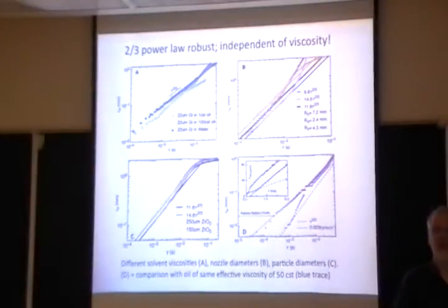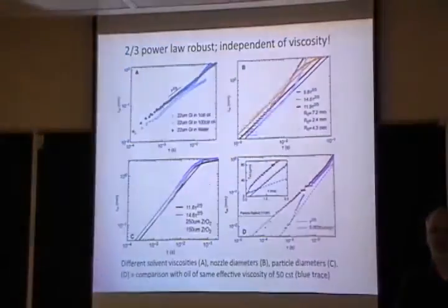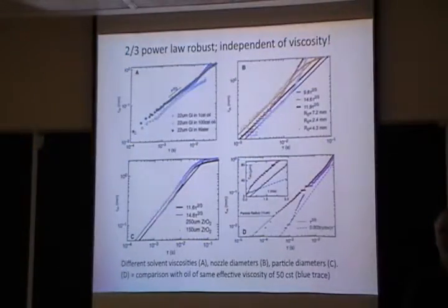Yes. What about surface tension? Yeah, the surface tension will matter. Is this all perfectly wetting? So it will matter, and surface tension is the key ingredient, right? But you know that from dimensional analysis already. If you have a t to the 2/3 power law, I showed you that last time, and you have width and you have time, you know, you want to do dimensional analysis, surface tension is key. Surface tension, but not viscosity. I'll show you how surface tension comes in.